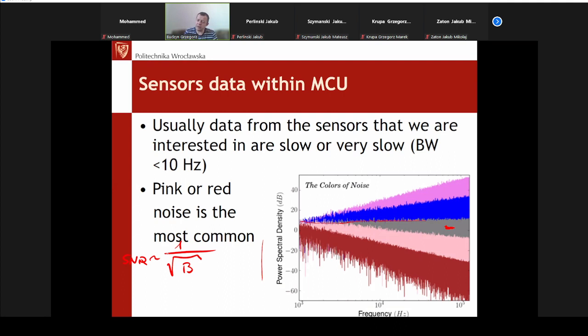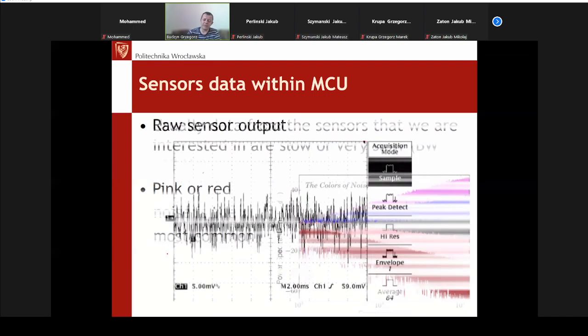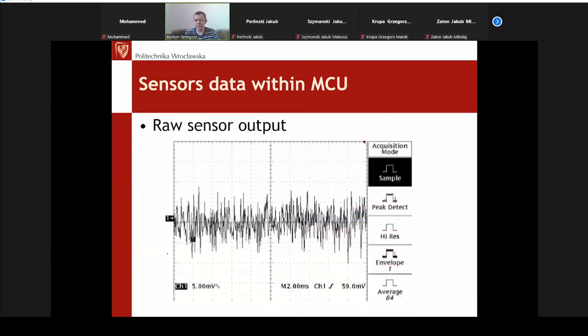So the narrower the bandwidth we have, the larger the SNR we can have, and the higher the quality. So we can improve the SNR by reducing the bandwidth, first of all with these anti-alias filters, the input filters to the ADC converter, and then when we have the signal digitally, we can try to add some signal processing, which we'll talk about more in a moment.